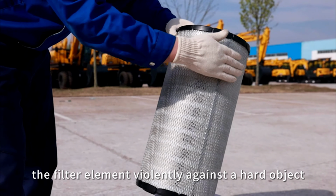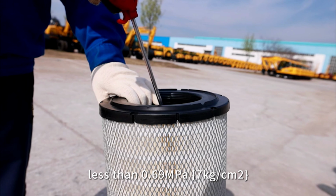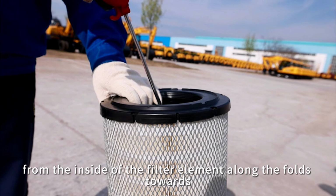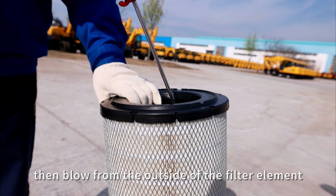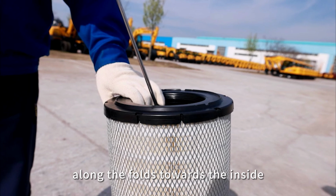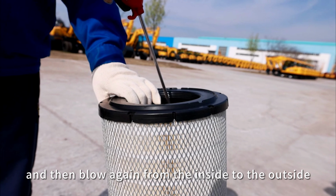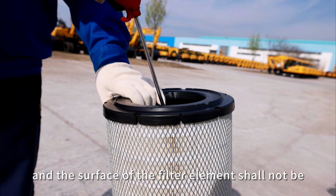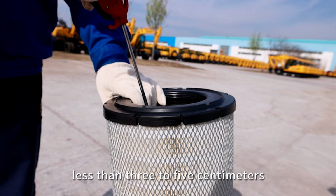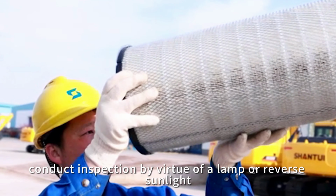2. Cleaning of compressed air: blow dry compressed air less than 0.69 MPa, 7 kilograms per square centimeter, from the inside of the filter element along the folds towards the outside. Then blow from the outside of the filter element along the folds towards the inside, and then blow again from the inside to the outside. The distance between the nozzle and the surface of the filter element shall not be less than 3 to 5 centimeters. 3. After cleaning is completed, conduct inspection.